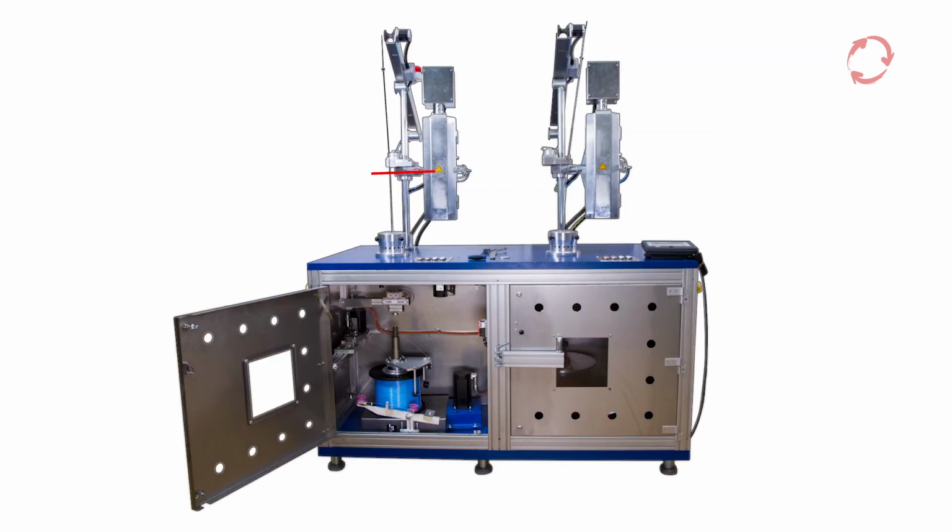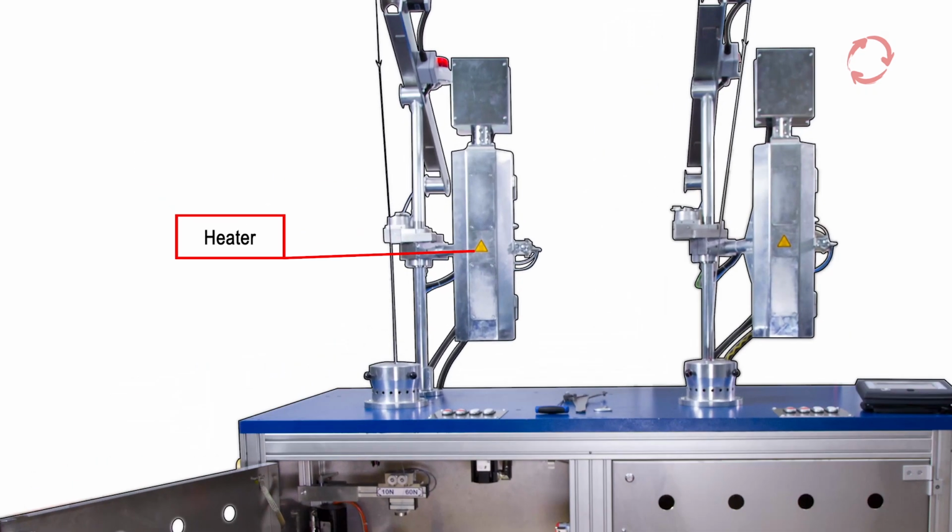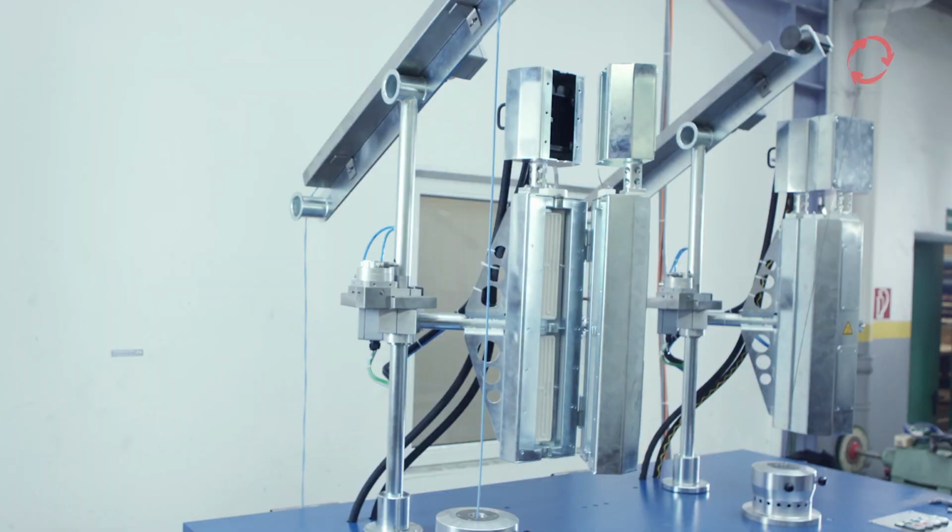The spiral passing through the mandrel is fixed in the heater, meaning that the spirals are heated in order to prevent them from twisting or springing back onto the mandrel when leaving it. Ceramic infrared heating elements are located in the two-section heater housing. The control system monitors the temperature in the heater via two thermocouples and adjusts it where needed. The heater is preheated before the process begins. Once the target temperature has been reached, the winding process can begin.